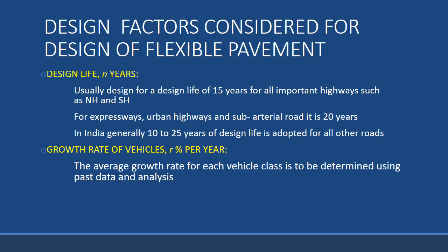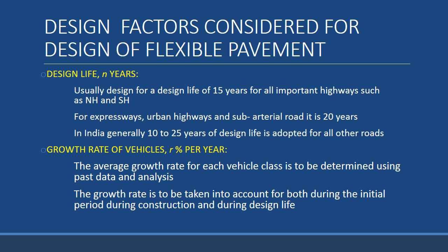We have to do an analysis based upon past data, like how much population is increasing, how much vehicular movement is going to occur, and how much growth it is going to have. We need to have a study based on past data, and we have to analyze it properly. The growth rate is to be taken into account both during the initial period of construction of the pavement and during the entire design life.